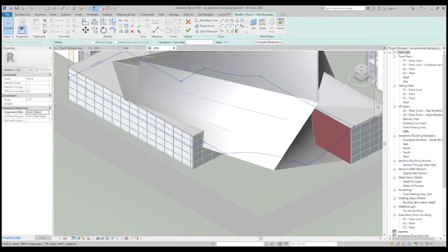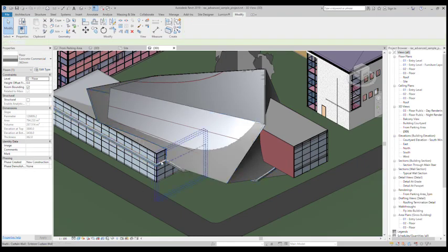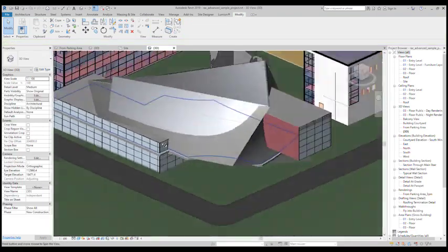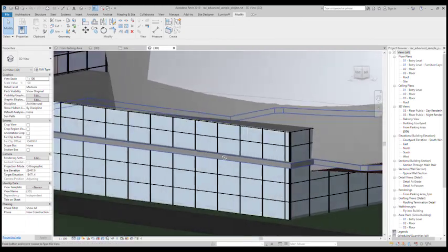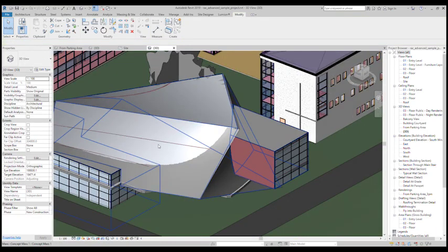So you use a negative concrete cantilever, so let's say 500. Now it's offsetting the floors by 500, right? Now it's sticking outside of the building, and that's a very specific look. You guys understand what I'm saying? Some architects do it like that. So whatever it is, your floors must either overshoot your walls or be on the inside of your walls. I don't want to see them on the face of your walls.